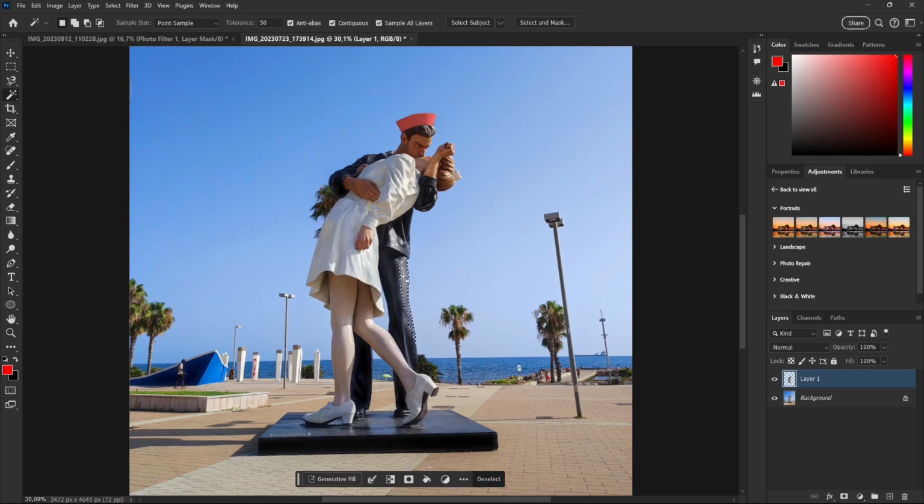If you click here on the black, it's going to look for black, and so on. Now you can adjust the tolerance. If you decrease the tolerance, it's going to get less pixel variation in terms of colors. If you increase this value, it's going to take basically everything. If you say 255, which is almost the maximum range, you need to find something in between when you need to select something real quick with one single click.